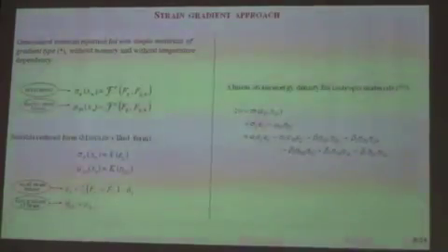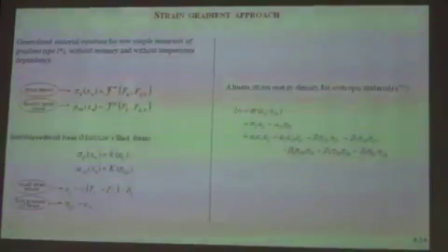Then we can build, for example, a linear strain energy density for isotropic materials that is a function of, as I said, the small strain tensor and the first gradient of it. By linearity, we multiply the stress and strain measures, and we see that we have two material parameters for the isotropic case in the strain regime due to the symmetry of the strain tensor.